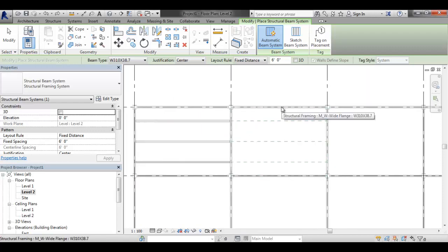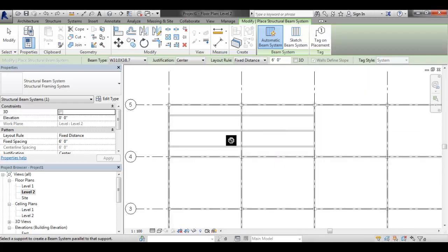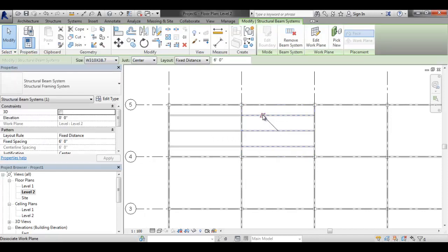And then on this one, maybe we'll do automatic. Now maybe I want to do a hurricane frame. So hurricane framing is all the beams go one way in one bay, and then I turn the beams and have them go the other way in the next bay. So I alternate that, and that's my hurricane framing. Gives a stiffer, kind of rigid system. So I'll go ahead and edit my boundary.